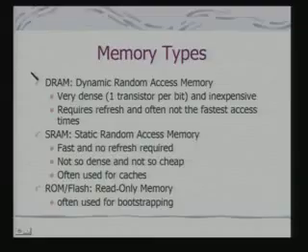Further, we can look at their divisions into dynamic RAM, DRAM, static RAM, that is SRAM, and ROM or flash, which are read-only memory, and read-only is often used for bootstrapping. In fact, flash has some characteristics so that we can even do in-circuit writing as well. So they are not strictly read-only, but their primary usage in applications may be for read-only purposes. Here we have a comparison of their characteristics.